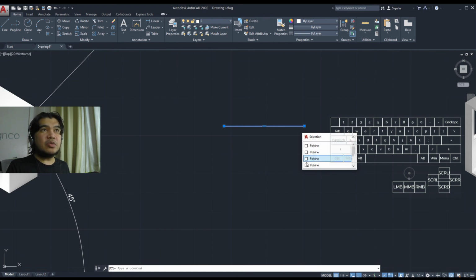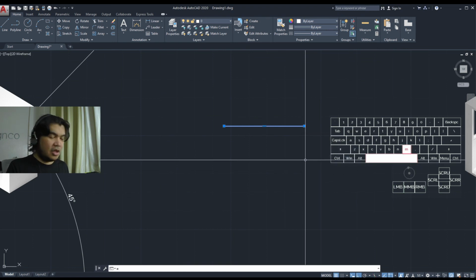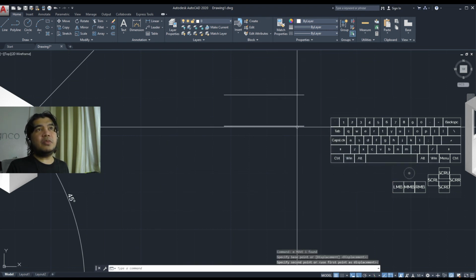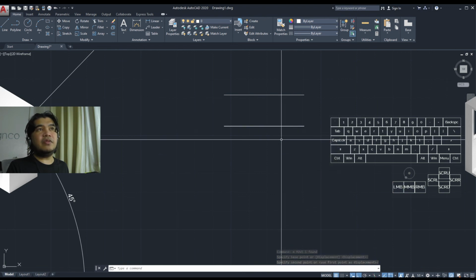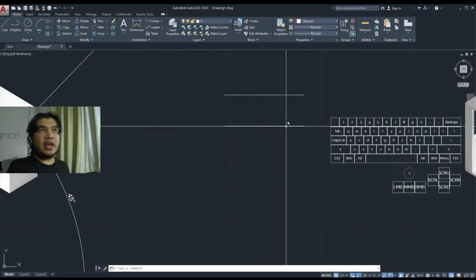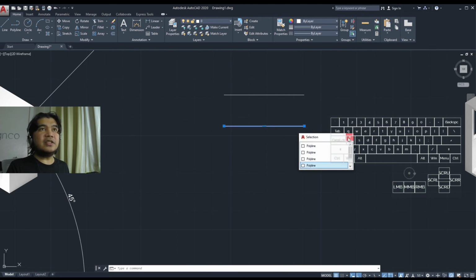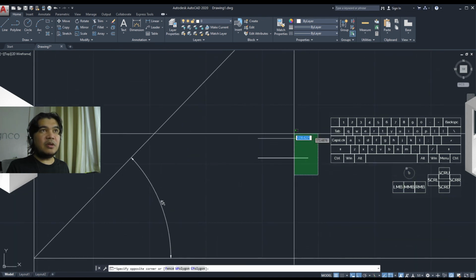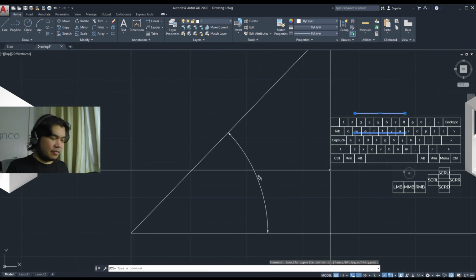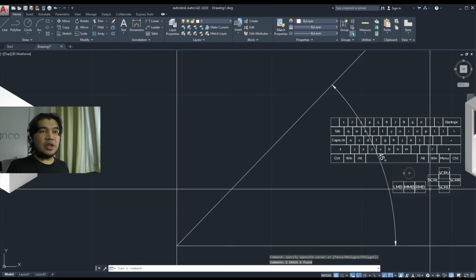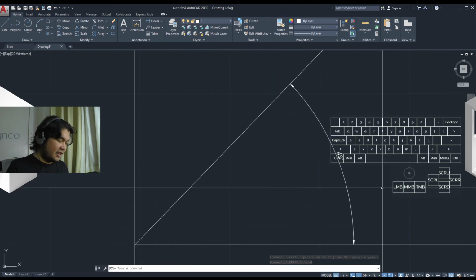So it allows us to choose which polyline, and since we don't know, just select one anyway, and we'll have selected number 3 polyline of this 6 or 5. So that you see that icon there that appears right near the cursor, that means there are multiple items here, and if you select and that is on, you get this list. Okay, so those are pretty helpful drafting material, drafting settings rather.